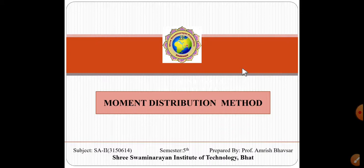After that, we put the conditions of equilibrium. From that condition, we will get the rotation of a particular joint, that is called EI theta, which will help us in finding out the support moment of each support. So for finding out the bending moment in the slope deflection method, we use different steps.